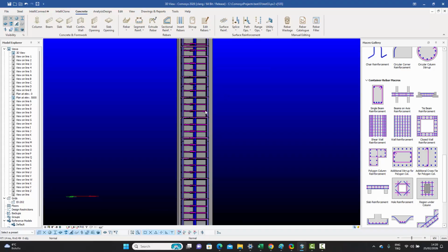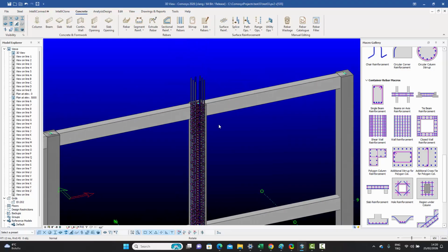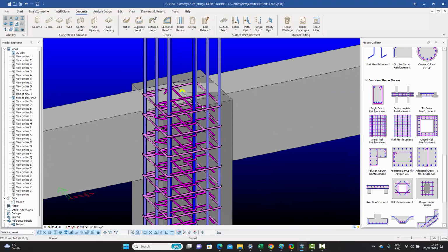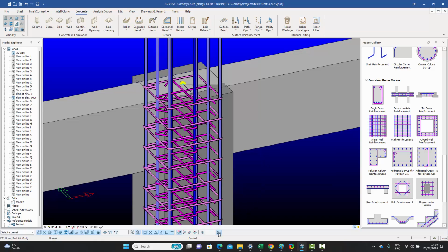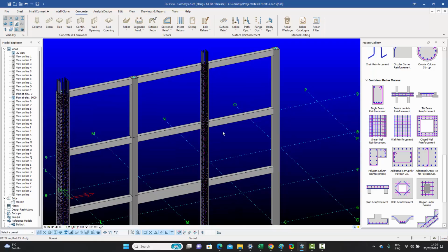In fact, you don't even want to show the cross ties in this view of the column in the column drawing. But this is, like I said, going to vary from person to person. You have both options. You can modify the ranges, for example, for this cross tie. If you wanted to, you could select this one and pull the range back a bit so that they don't clash. But it's an extra effort, and it's not even needed for the quality of the drawings.